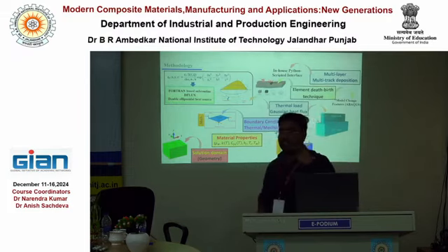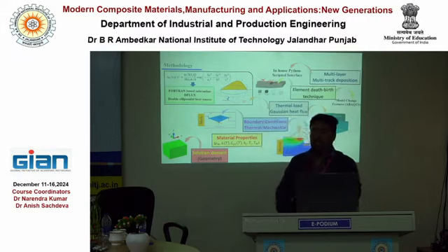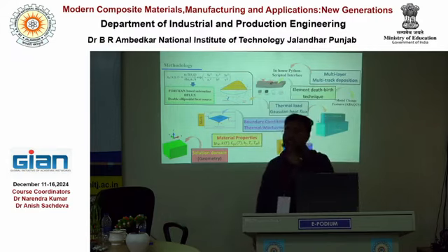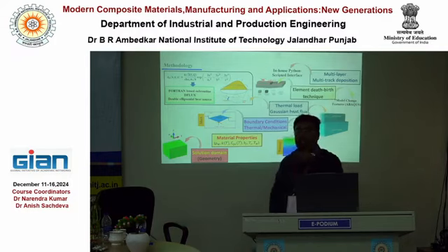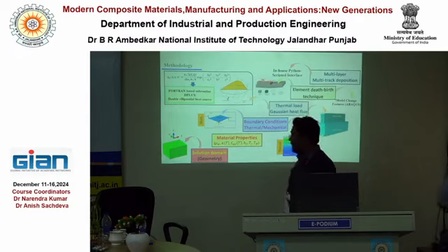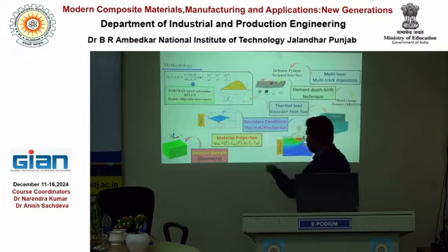In the thermal boundary condition, there are three aspects of heat diffusion from the material: conduction, convection, and radiation. All three come into the picture if we are taking care of temperature assisted processes. Since deposition is going on, we have to deal with the melting temperature of the material. At that point, these three modes of heat transfer, conduction, convection and radiation, will come into the picture as thermal boundary conditions. So we need to incorporate these three boundary conditions. The associated equations I will show you later on.